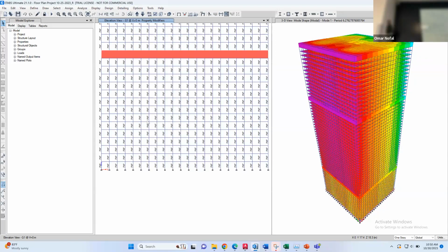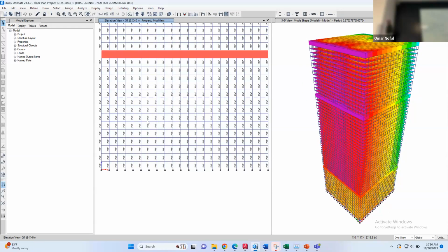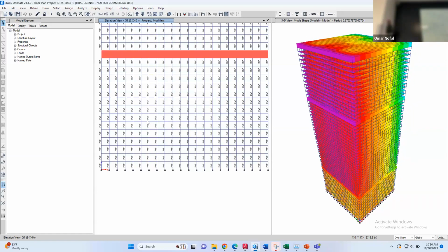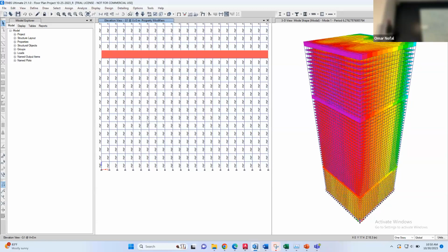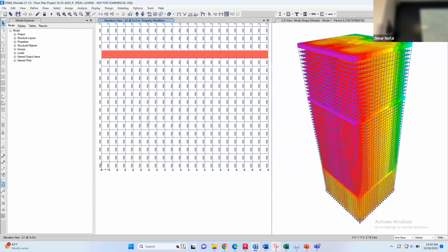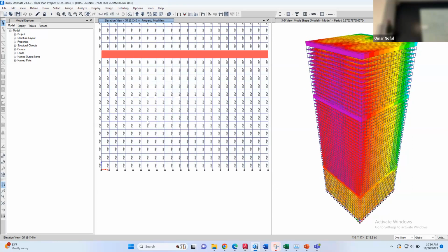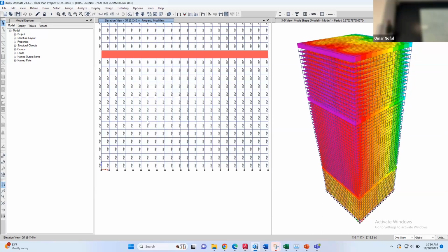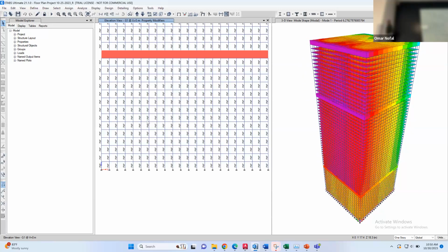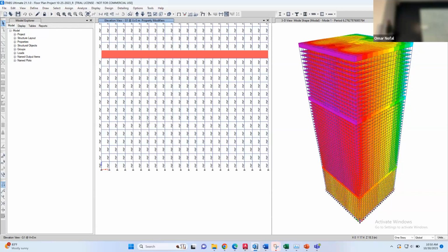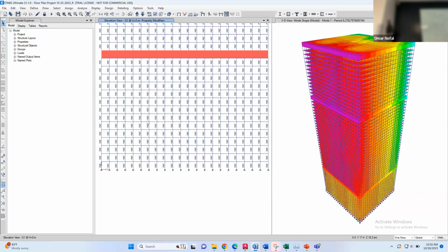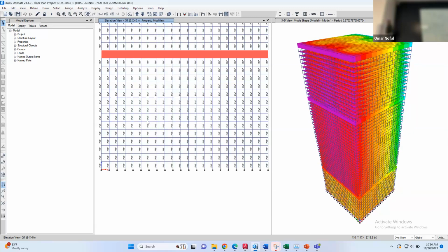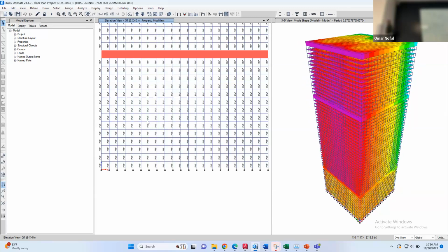You can replicate it in the story where this bracing stops, because it's much better for the bracing to connect to the outrigger, as it connects with a stiff element. When you push the building, the bracing is connected to a very stiff story. And also the bracing should connect to the columns on the four sides. So here and the other side. What if, when we do it going upward, it doesn't connect to the corner of the top? It doesn't have to go to the corner of the top, it can stop at any story.